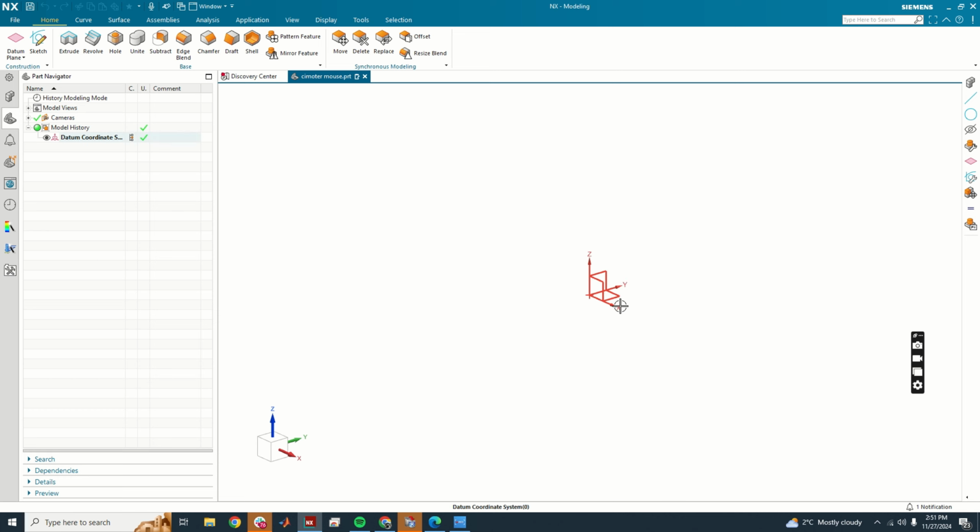In order to lay out the basics of surface modeling, a really good way to do things is to think of sections and ribs for where you want your surface to attach to. So we're going to basically set up a bunch of different sketches, and the surface that we put onto the sketch is kind of going to be like a cloth that drapes over top of our sketches. So the very first thing that I'm going to do is just draw a basic outline of a computer mouse in a couple of different views.